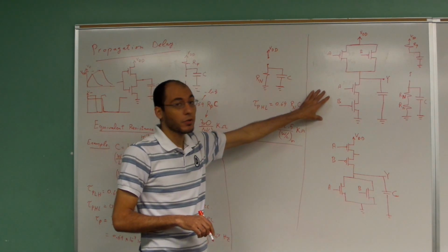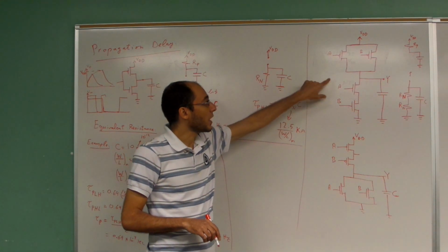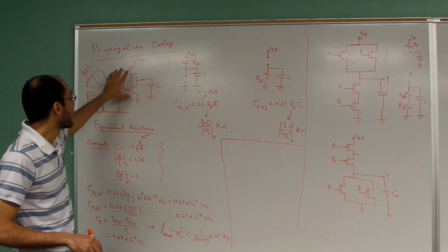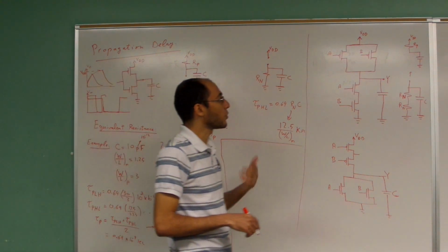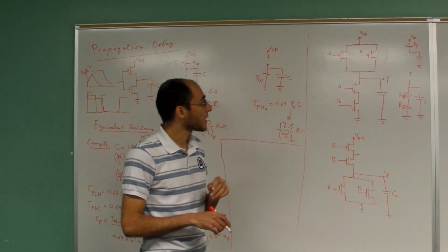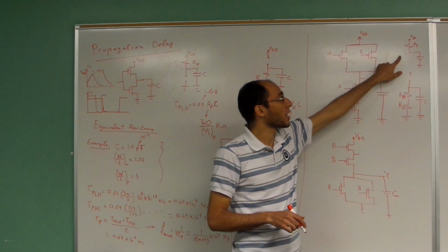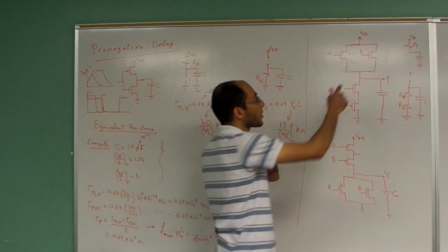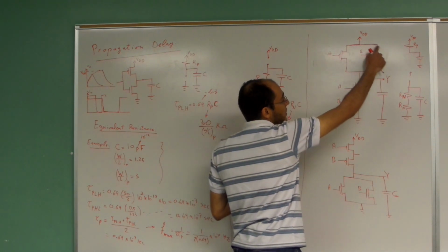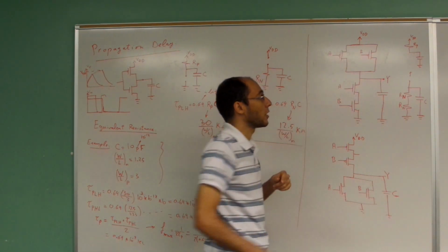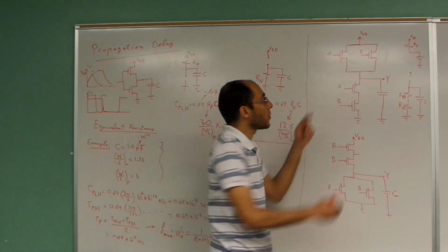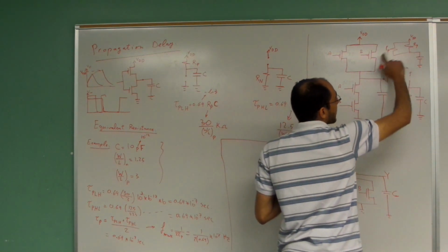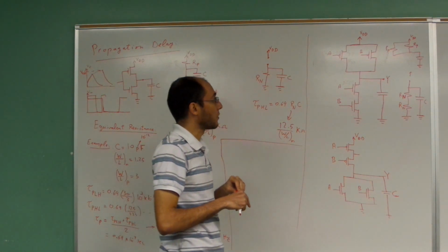So what if we do not have an OR gate? We have another gate. We do not care what it looks like, but it is not as simple as this gate was. It has a number of MOSFETs, not only two. In that case, for the propagation time from low to high, you do not expect to see Rp only, one value only. Why? Because either this transistor is going to be on, or this transistor is going to be on. If they both are on, then you might expect to see two resistors Rp here, and thus the equivalent resistance is half of this value, right?